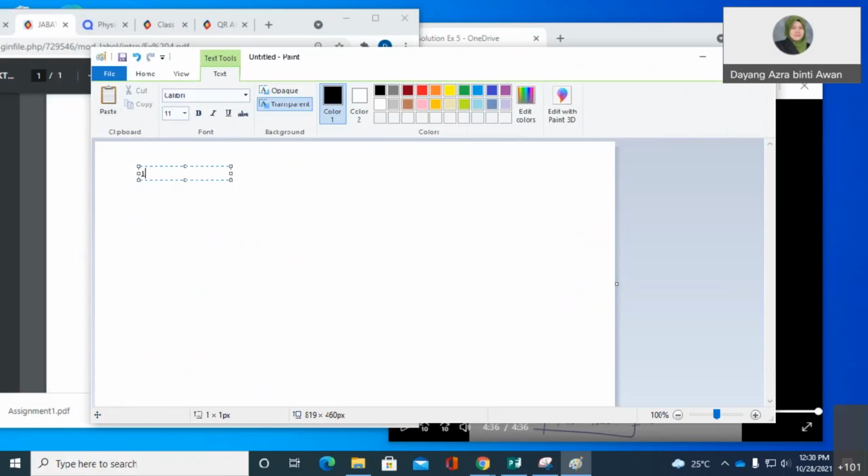Okay, so we have 1 divided by R total is equal to 1 over R1 plus 1 over R2. This is the formula for parallel. For series, we just have R total is equal to R1 plus R2. The detail of the formula you will learn in circuit theory later. For this you cannot find the answer. You can find the answer of the resistor, but you cannot find the error because we have no calculation for error if it is 1 divided by something.